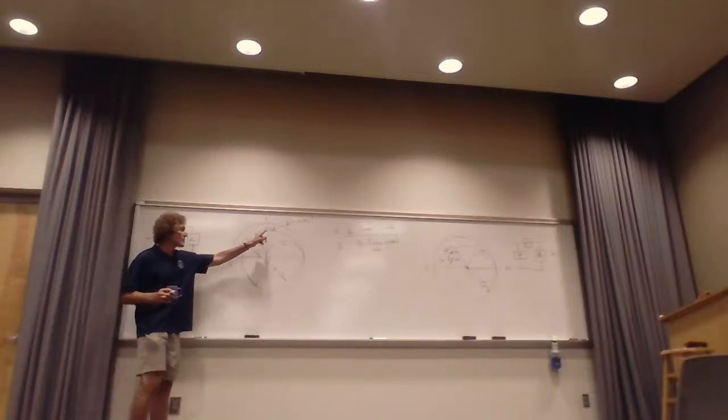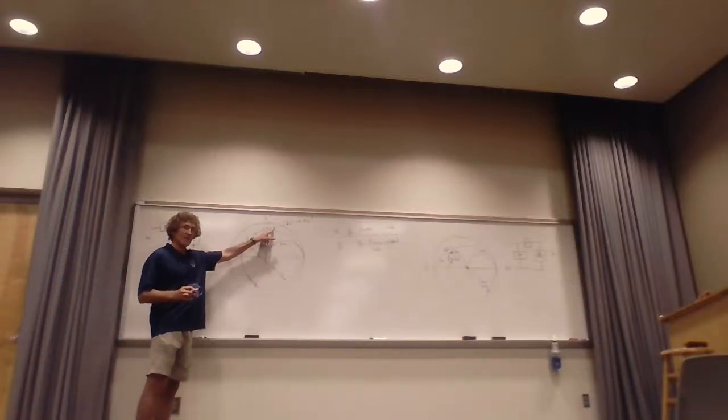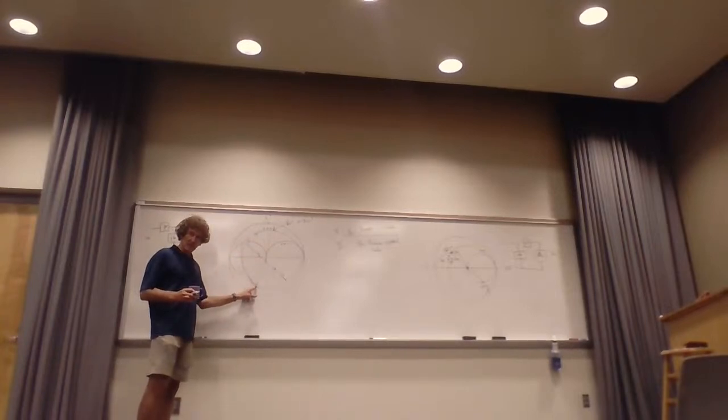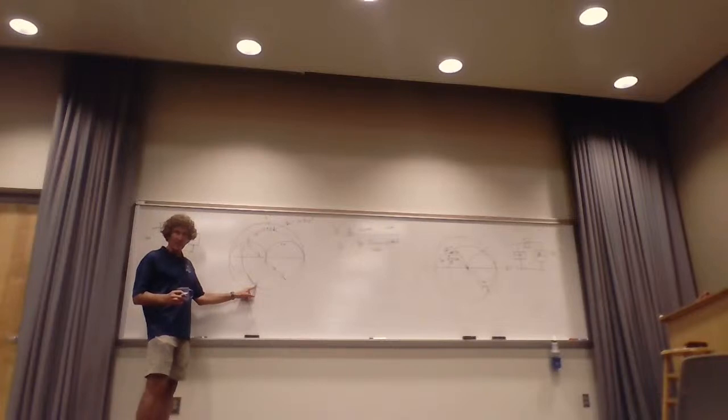We're in the impedance domain here, right? Anything we add is in series here if we stay in this domain and move. But if we don't want to work in the impedance domain, we want to add things in parallel, then we take 1 over that. Now we're in the admittance domain, and anything we add is going to be in parallel. Y'all follow me? All right.